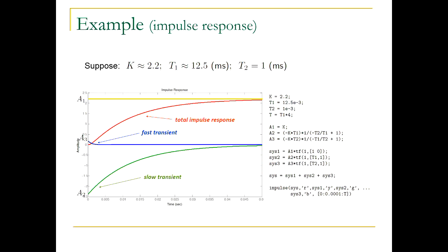Okay? So what can we see now? If I apply an impulse input, what does this mean? It's like I have a switch for the voltage. I apply an infinitely large voltage and then I just turn it off. If you apply such an impulse input to the system, the shaft will move and then converge and stop eventually, converging to a certain value. The shaft angle changes from 0 to some value. So that's what we just learned. This is very physical, right? If I apply an impulse voltage, the shaft will move and exponentially converge to a certain value.